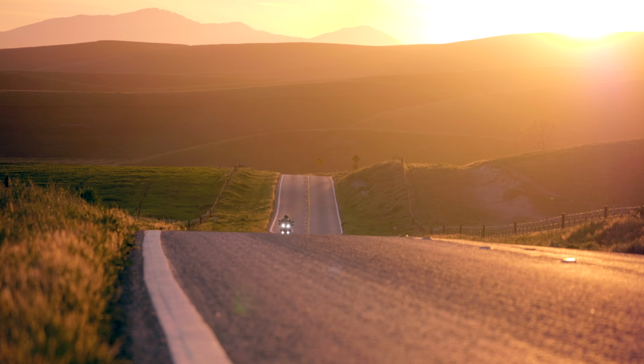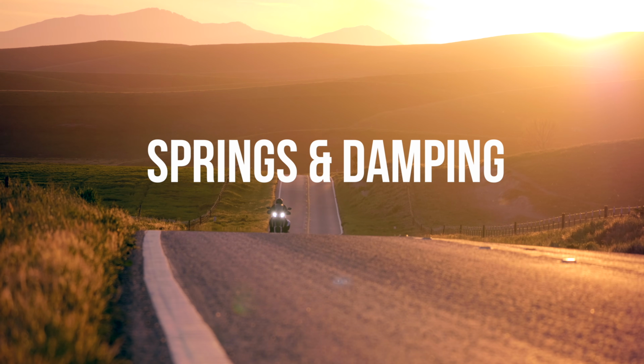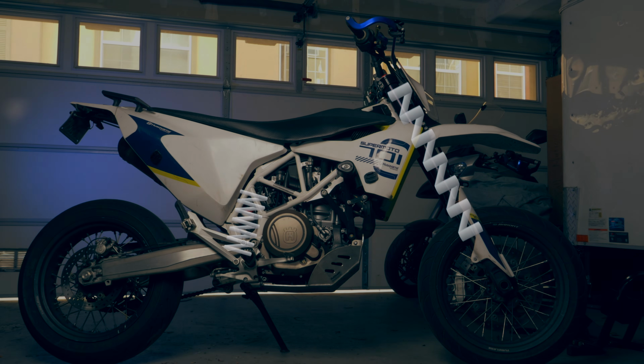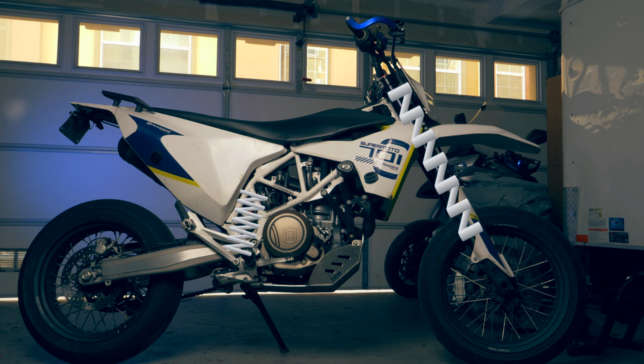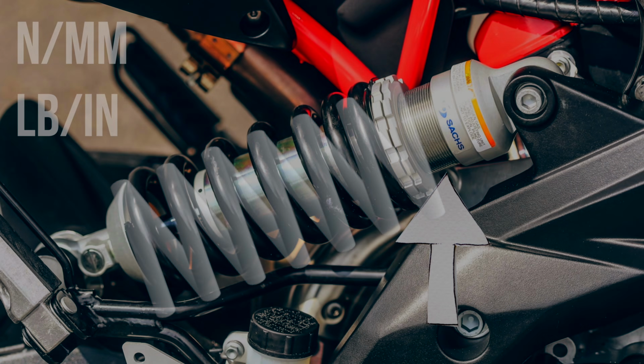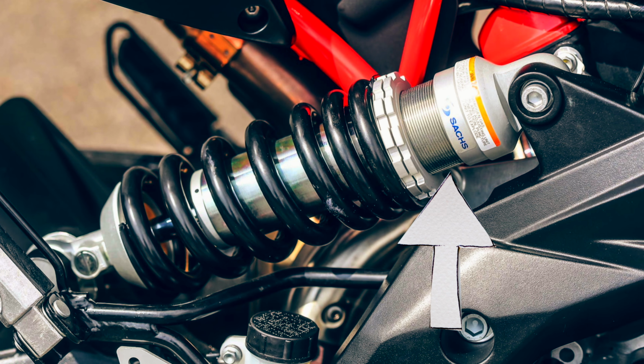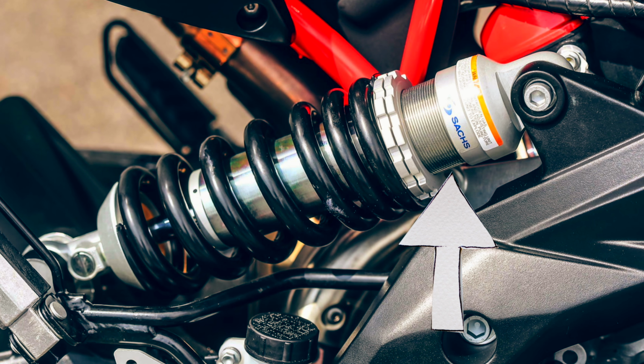So now that we understand basic tire traction, motorcycle geometry, and the front and rear ends of motorcycles, it's time to tackle springs and dampers. As we talked about earlier, both your front and rear suspension have springs, which have a certain spring rate. The spring rate is the stiffness of the spring, commonly measured in newtons per millimeter or pounds per inch. These springs are set up from the factory with a certain amount of preload, which means that the spring is compressed a small amount from its free length.